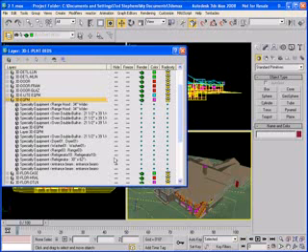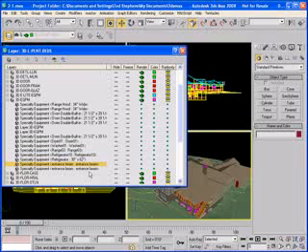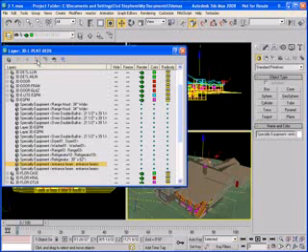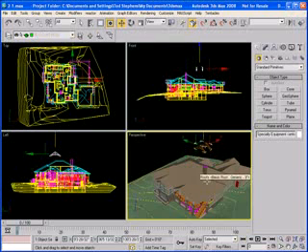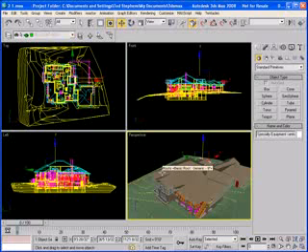Let's now go down under 3D equipment here, and say that I wanted to select one particular piece to either change the geometry or add a material. I can just click on it here. There's this entrance beam, again just a specialty object from Revit. I'm going to click to select it in the viewport. And again, just another example, I can go to my Move command. I'm in my perspective view, I just hovered over the Z gizmo and moved it straight upwards.